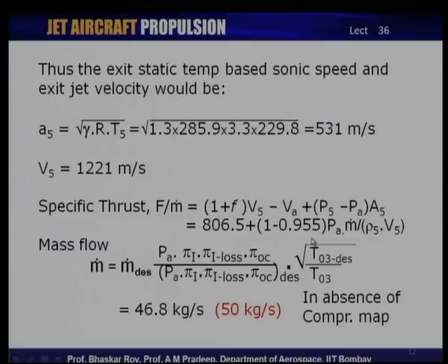However, the pressure thrust calculation requires the values of mass flow and also the density, which of course we can calculate from P 5 and T 5, which we have already completed, and V 5, which is available with us. So, rho 5, the density, can indeed be very quickly calculated, but we need to quickly find the mass flow which is passing through the engine. Now, calculation of the mass flow requires again a little more